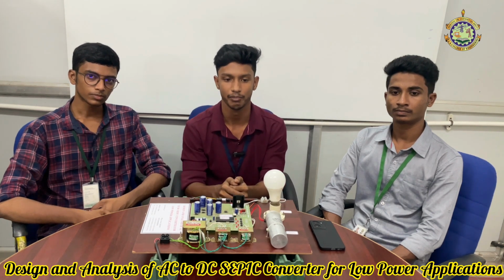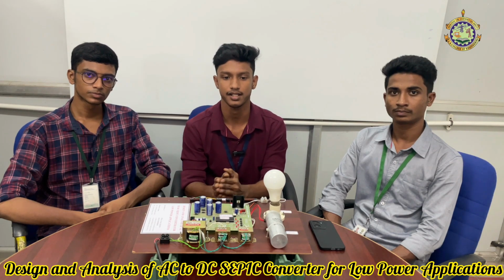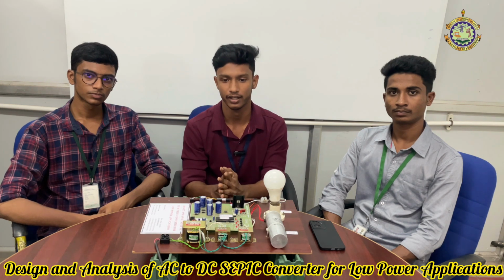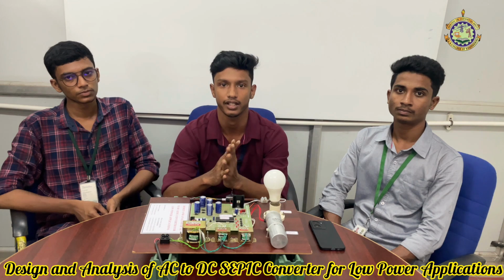During the on period, the switch is on, L1 gets charged and C1 discharges through L2, and in the off period, the stored energy is released via L2 to the load. This can be explained in the MATLAB simulation and also in the hardware components.